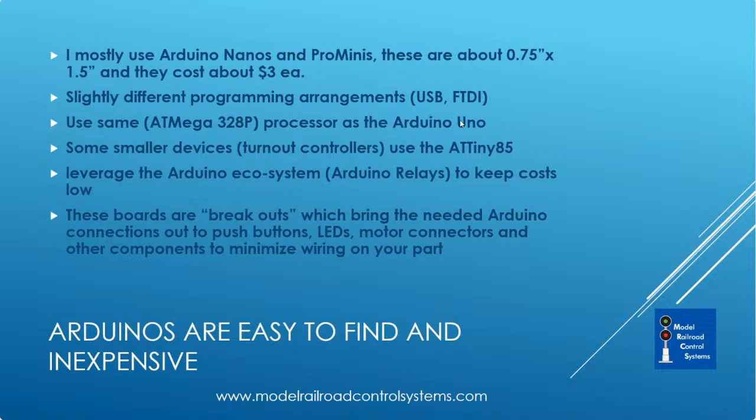The types of boards we're building are generally referred to as breakouts, which means we take the core device, the Arduino, and a few of the key things that are needed for that circuit, and we break out the connections to terminals and so forth, so it's easy to interconnect them. And the idea is minimizing wiring under the layout, making it much easier to install and maintain the systems.